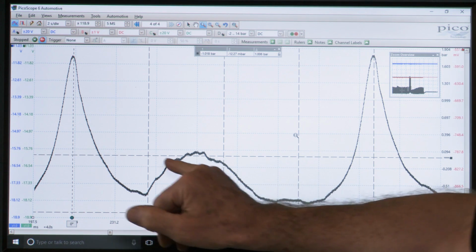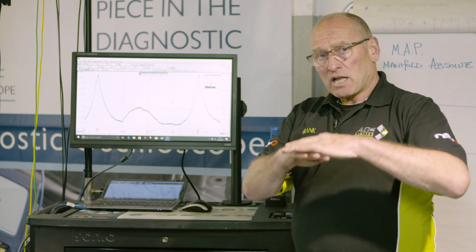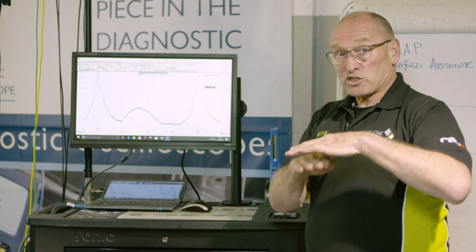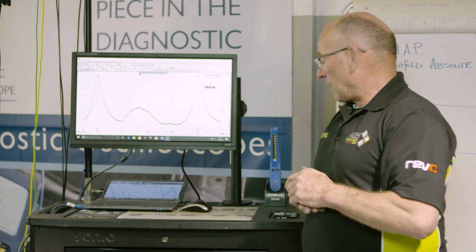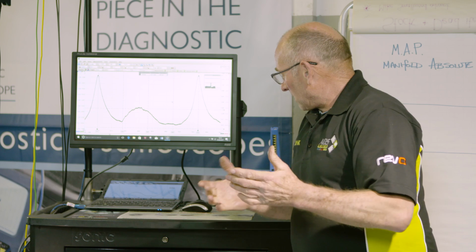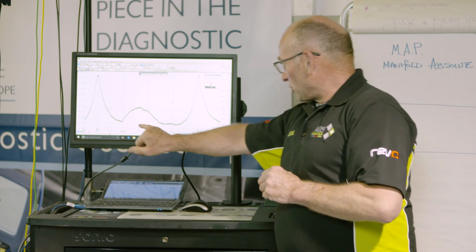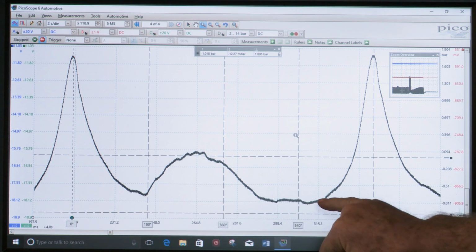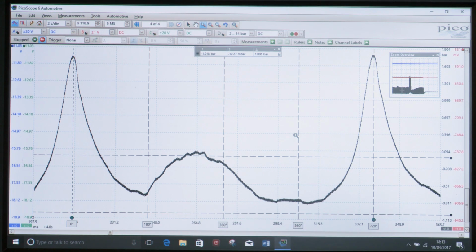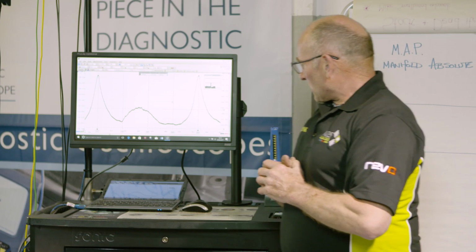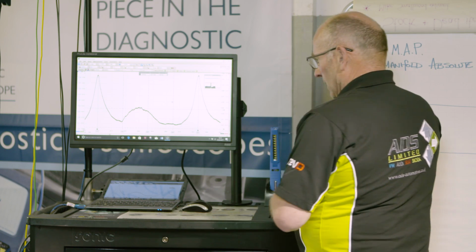So this actually reflects on the efficiency of the seal in the cylinder as the piston falls or is actually being pushed down. So that is an efficiency statement, if you like, during the power stroke, and it should more or less equal this zone here. Well, this is the intake event, if you like. We'll come to that in a moment. So, okay, we can see that we have quite a healthy period.